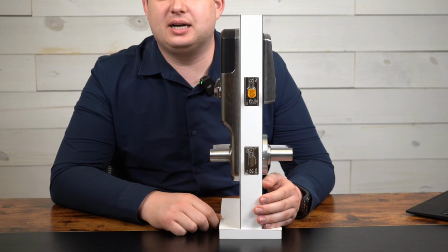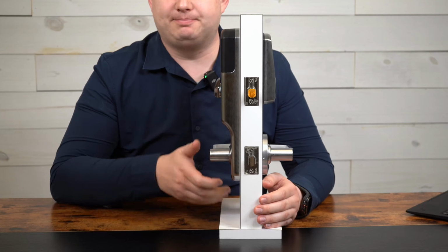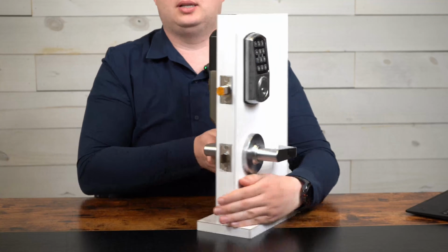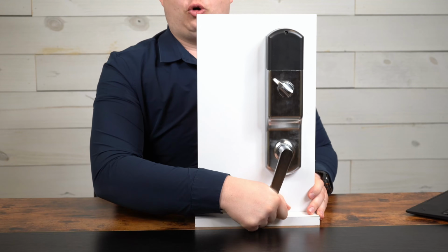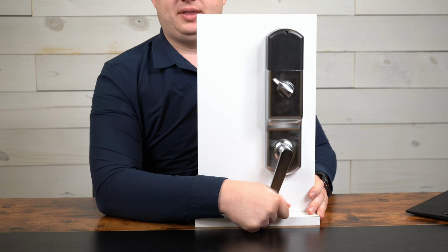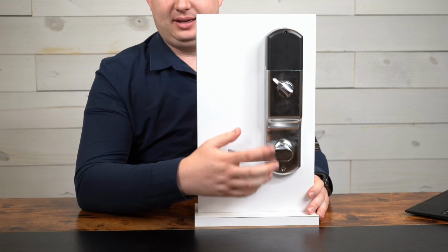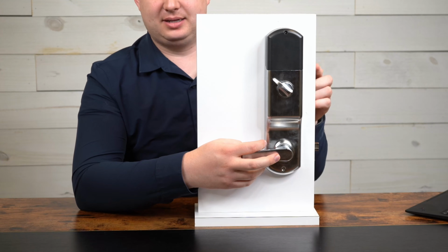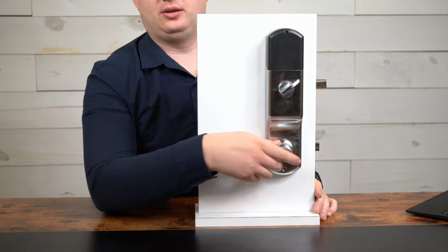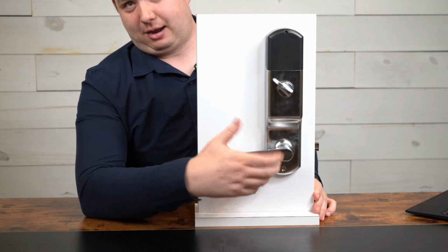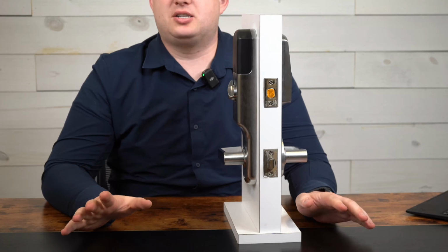Now the difference here is that the latch bolt and the deadbolt are connected inside of the body. So when we, let's do this way. Here we go. So when we open the door from the inside, you can see both the latch bolt and the deadbolt retract. And then the latch bolt re-extends, the deadbolt does not until I relock it, at which point you will need to unlock from the inside or the outside. So it's a little more involved. It's nothing complex, it's just 2 in 1.